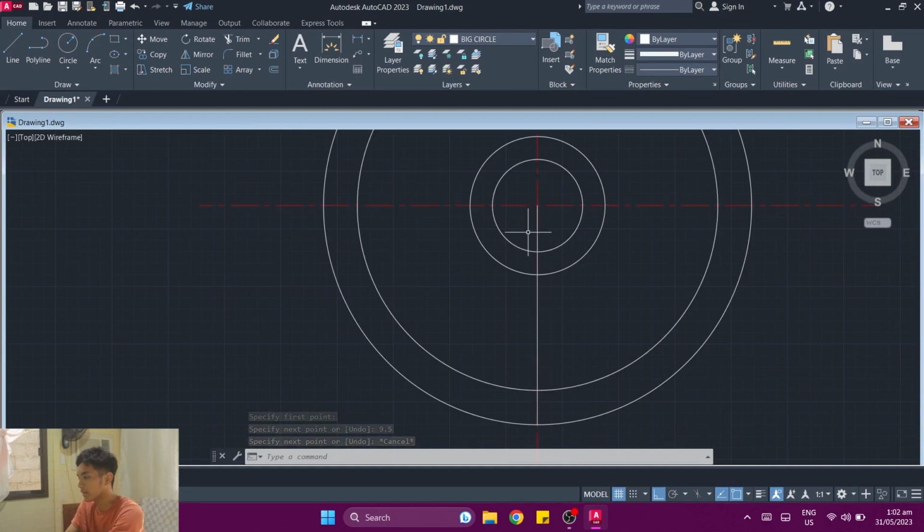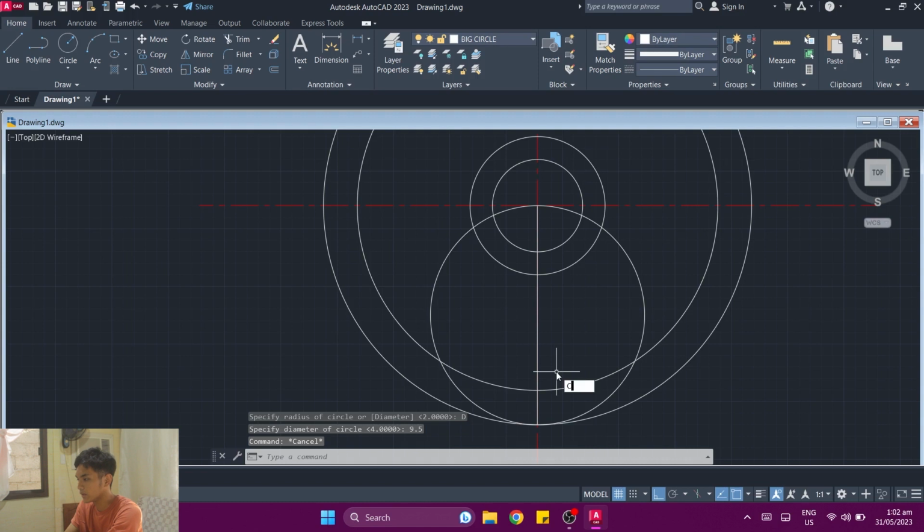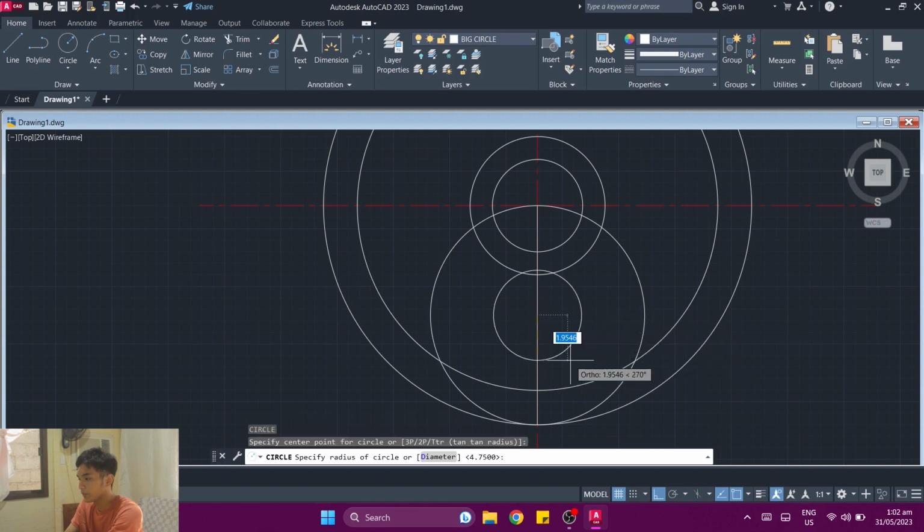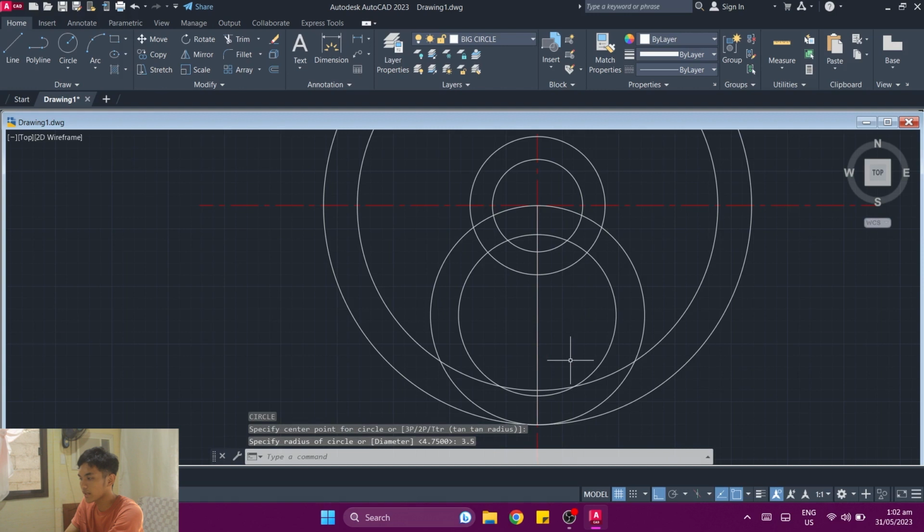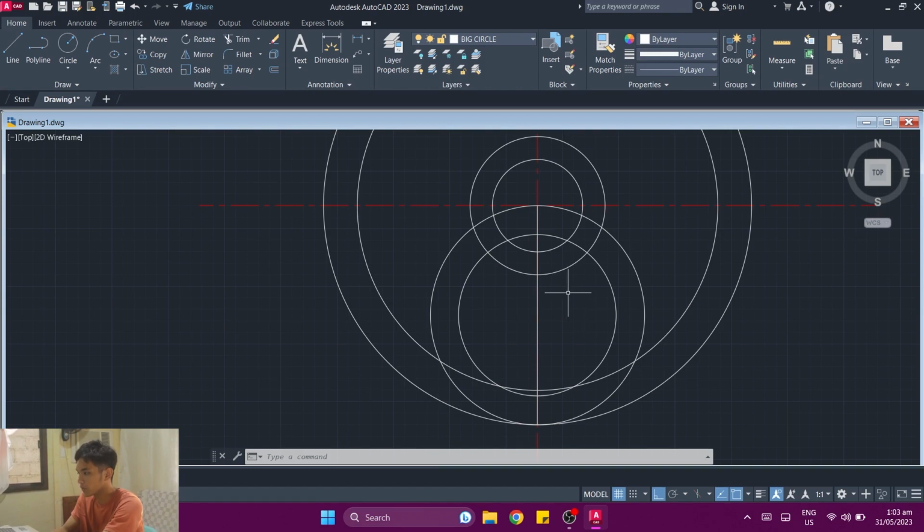We now create circles with 9.50 diameter and the radius of 3.50 respectively from its midpoint. So from this point on, we will be creating the smallest circles in the figure. We would be utilizing TTR in order to make them. TTR, or tangent-tangent radius mode, is used when you want to create circles that are tangent between two existing objects. Tangent meaning it touches such an object at one point. So for instance, our first circle should be tangent to this arc and this arc.